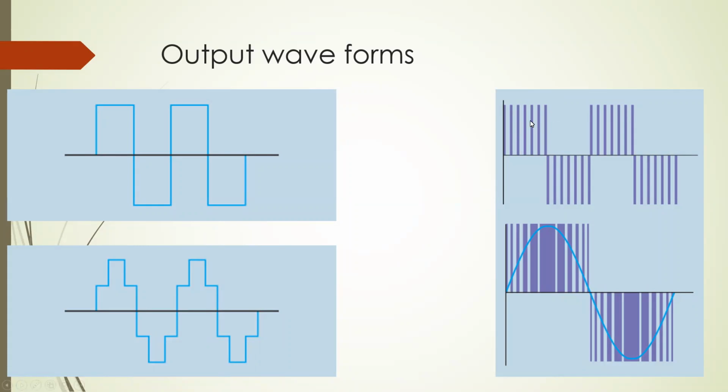It'll be pulsing up and pulsing below, depending on which set of the IGBTs turn on. And then we're going to adjust the width of the pulses. And so we see here in this first pulse, it's not on the full time, but the sine wave is very low. And as the sine wave is supposed to get greater, the pulse widths get larger.